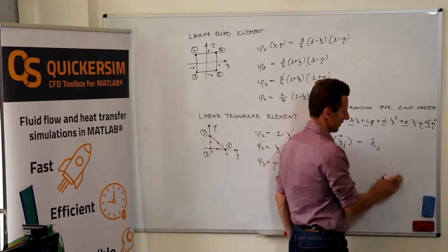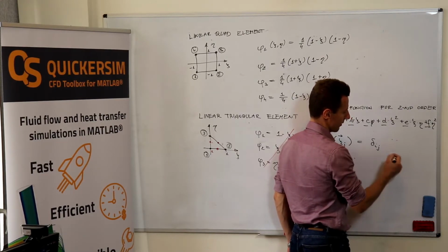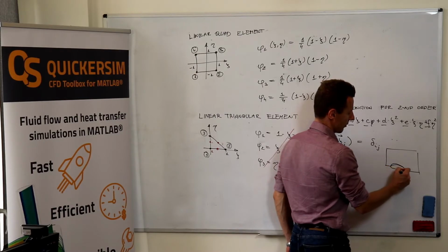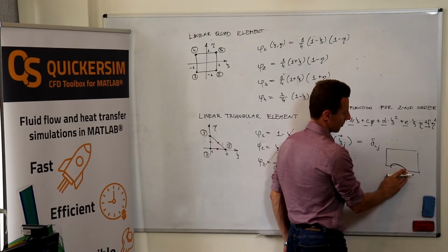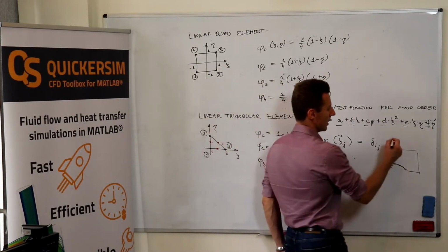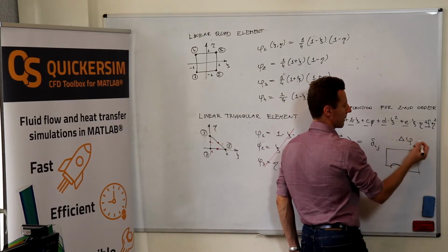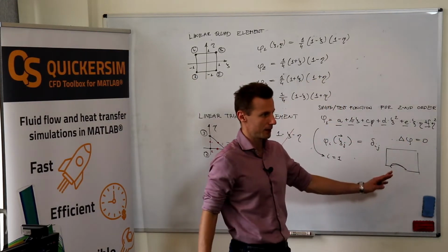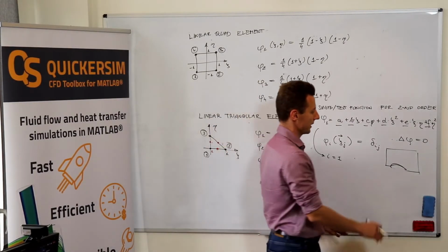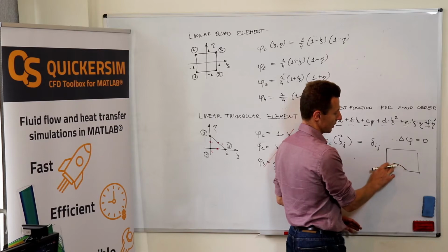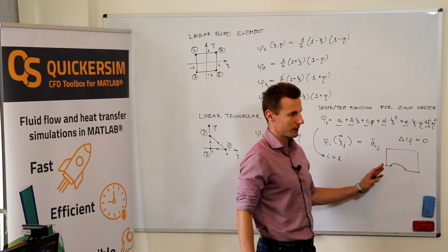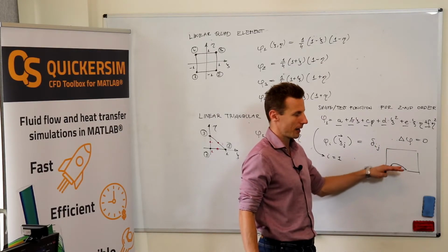There are two problems, and I have investigated it once with a very simple example. If you want to solve even the potential flow over the airfoil, if you've got potential flow, this means that you write the Laplacian of the velocity potential. So you basically are solving a diffusion equation. And we did something like that. You can use first order, second order, 8th order, 10th order finite elements to solve that flow and calculate the pressure